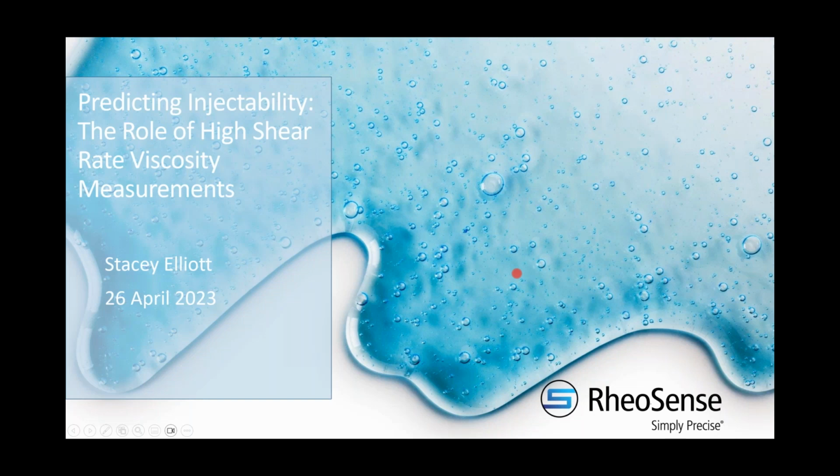Okay, so let's first go over what is steady shear viscosity and how does our particular technology obtain this viscosity value. VROC stands for viscometer rheometer on a chip, and our technology is essentially a combination of microfluidics and MEMS, micro electromechanical sensors. And so we have a well-defined microfluidic flow channel, and at the base of our channel are 4 pressure sensors. We control flow rate through the channel and then measure the pressure drop across the length of the channel. And from these two values, in combination with the geometry of the channel, we can calculate the shear rate.